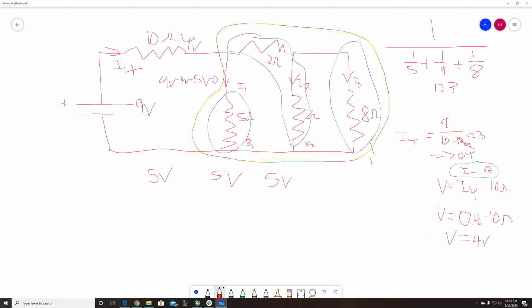This is so informal. Don't take this seriously. Don't call these big chunks in your true writing. Call them series parts or something more formal. It's just names. So with this knowledge, you know that for the resistors in each big chunk, you just need to add them all together. So you know the voltage, you know the resistance. All you're trying to find is the current.